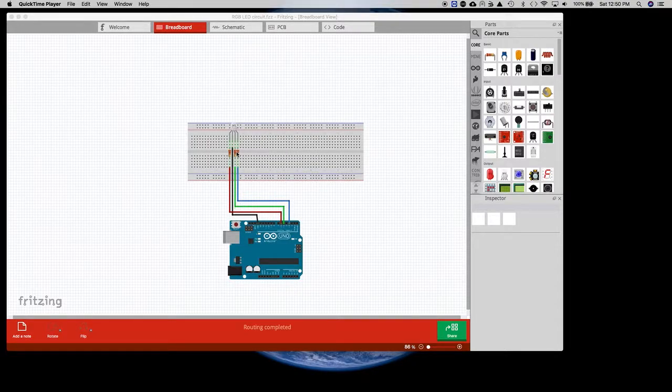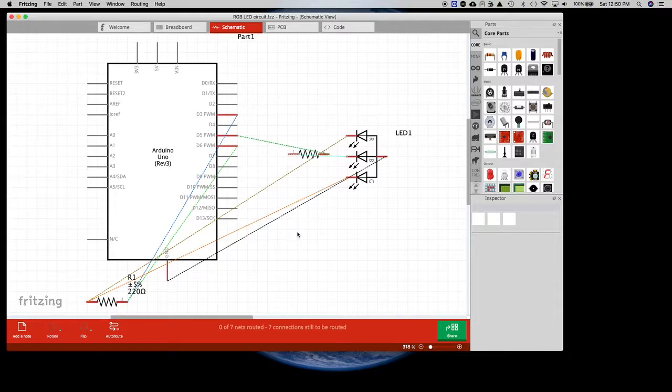So you've created your Fritzing circuit here, or I have, and if you want to make a circuit diagram from that, there's a couple of steps you have to do. First, click on the schematic here, which is pretty easy to find because you see this circuit diagram symbol of a resistor. And you notice that Fritzing auto sort of populates this space with circuit diagram symbols and wires all over the place. So you essentially have to clean it up, which is kind of a good exercise in understanding the circuit anyway. So there's some tools you can use to do that.